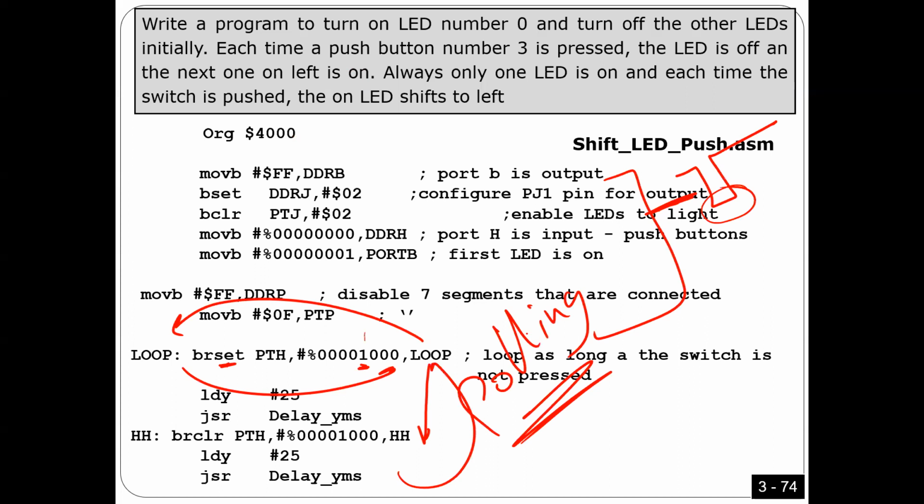You got it? So if you compare this program with interrupts, here I want you to learn 2 things. Number 1, usually, for one task, I can put it in the main program, or I can put it in interrupts. It's something I need to decide, okay? Sometimes it doesn't make a big difference, but anyway, this is something you need to decide. If your program has 3, 4 tasks, you have to decide which task has to be in the main program, which task has to be in an IRQ or timer or whatever, okay?